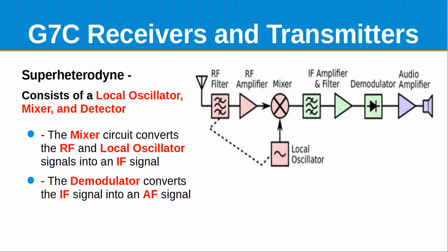That's called heterodyning. I think the term superheterodyne came about because they would normally have, at least for the higher end radios, more than one conversion stage or IF. So you'd convert it to a higher frequency IF and then convert it again down to a lower frequency. And it made it easier to amplify and filter the intermediate frequencies.